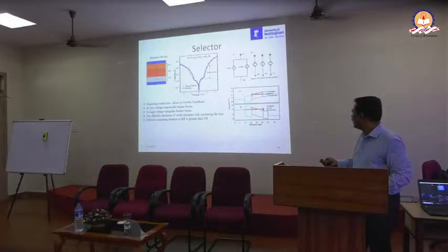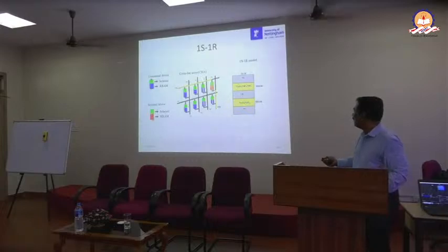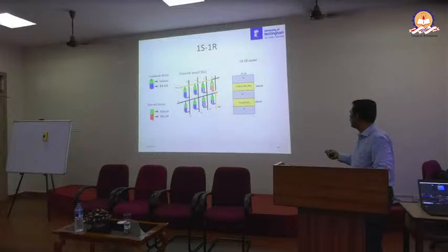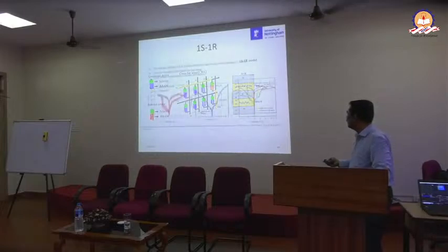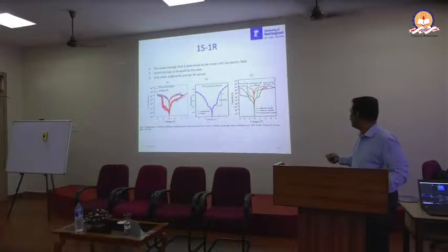This memristor has a selector device made of platinum, titanium, tantalum oxide, TaOx, TaO2 and platinum oxide. So the platinum device, its characteristics is shown here, and we also modeled it using a tunneling junction. We integrated the selector with the resistive RAM, and you can see the entire structure. This is the selector and this is your resistive RAM. It gives you a perfect result, whereby this is your memristor, this is your resistive RAM, and here what you see is the so-called selector model. The combination of these two gives you a new memristance device, something like this, whereby the switching voltage is from minus 1 to plus 1 volt. So whatever we exposed previously, we did it physically, a physical device we fabricated, and this is our result.